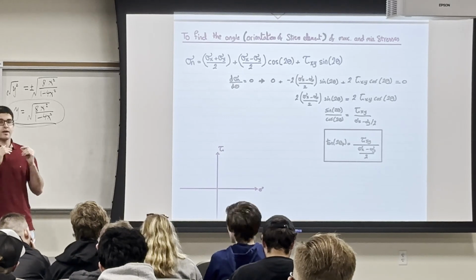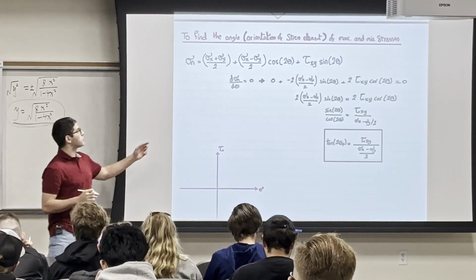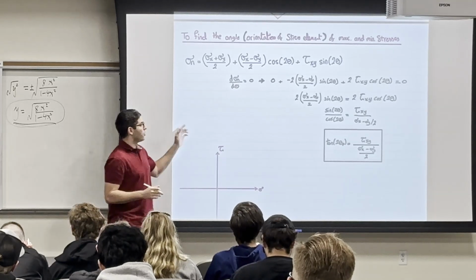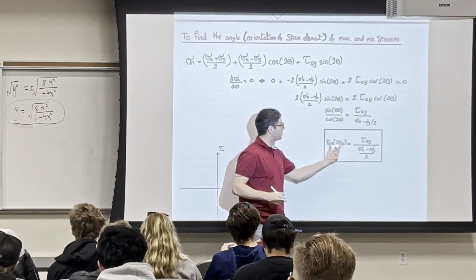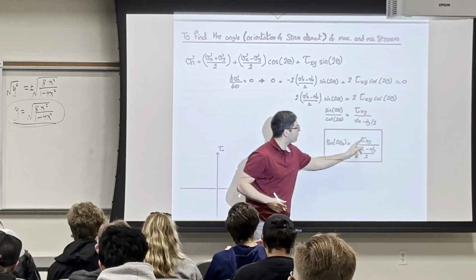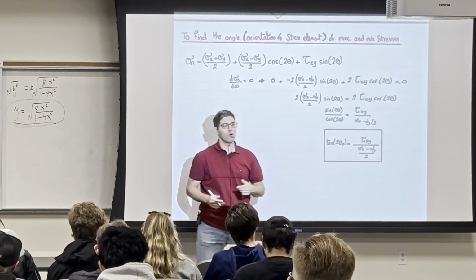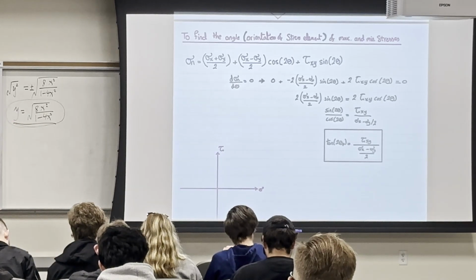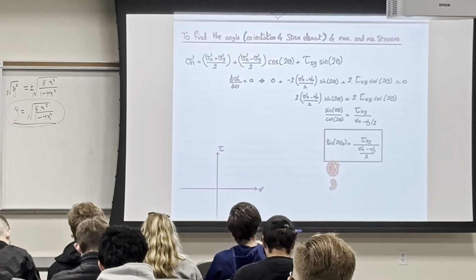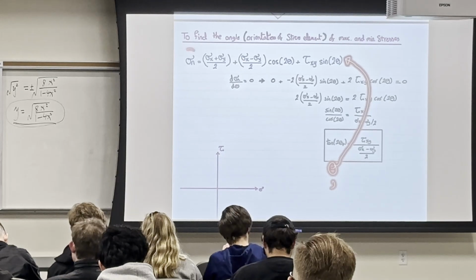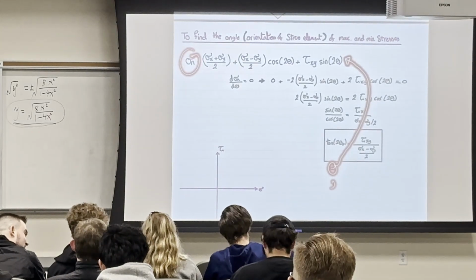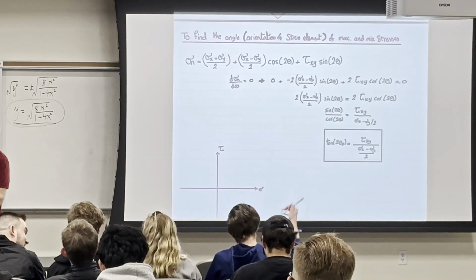So to get the angle that will give me the stresses at maximum and minimum, you need to take tan inverse of tau over (sigma x minus sigma y) over 2. This equation will give me the theta, and using this theta, if I substitute it here in the sigma n equation, I'm getting the maximum stresses. Is that clear? I want you to notice something.